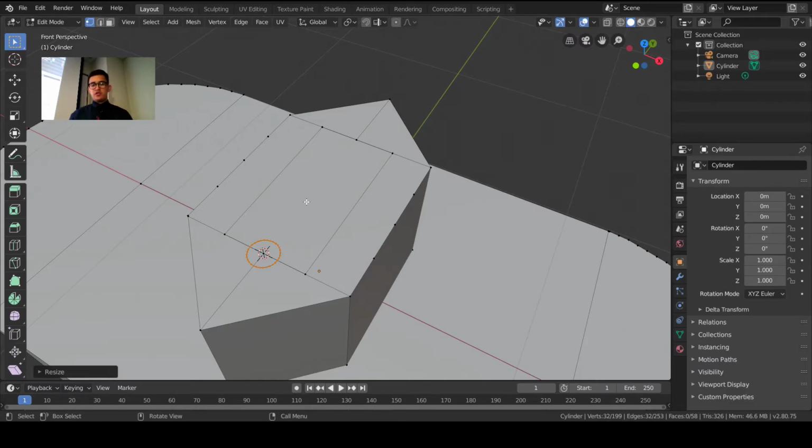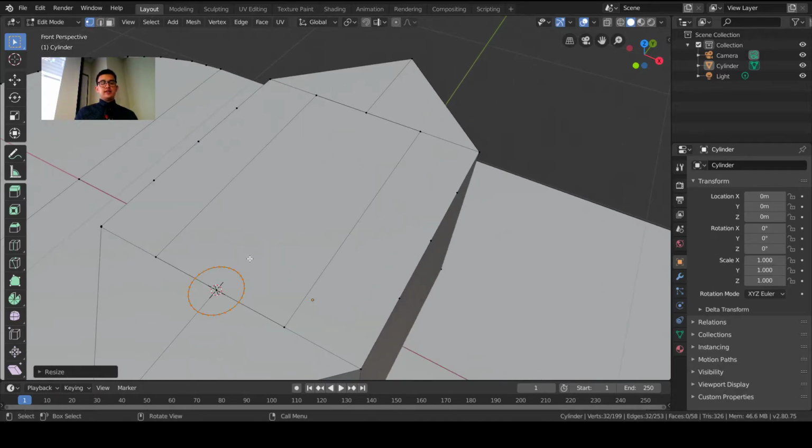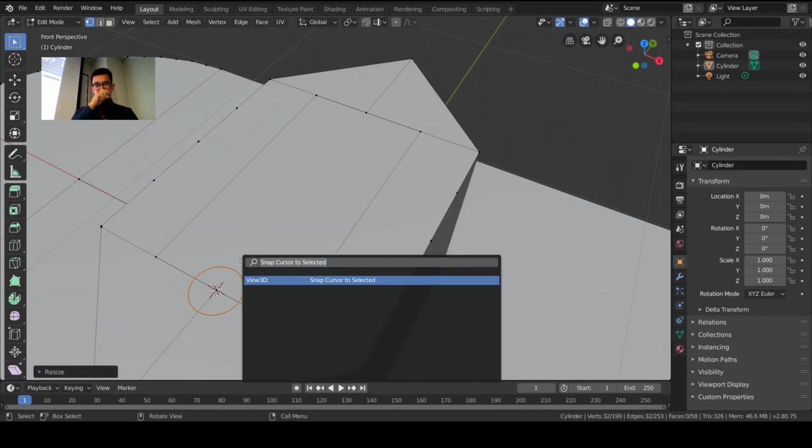And one thing I haven't showed you yet is the mirror tool, or the mirror modifier, and that can help a lot so you don't have to redo things twice. So I'm actually going to make these prongs a different object. So if you have your circle that you just made selected, if you are following along, you can separate it from your object by pressing spacebar and typing separate.